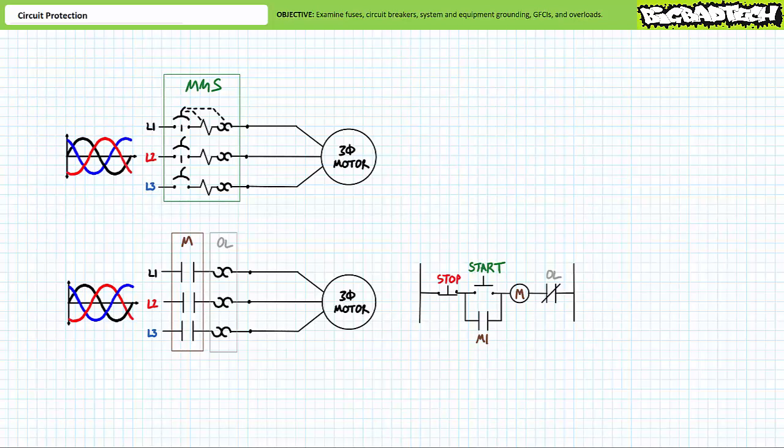High sustained current can heat up the wires and damage the insulation on motor windings. It is for this reason overload relays protect systems not from high current events associated with short circuits, but rather from sustained high current draw, where the key word is sustained. An overload relay will allow a motor or other device to briefly overload, but only for a given amount of time, before it signals enough is enough.